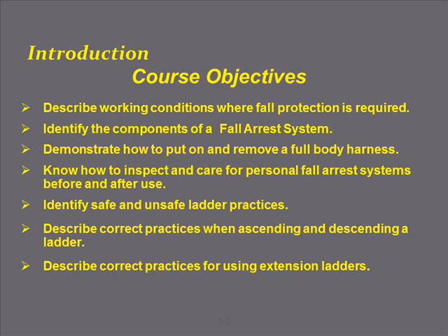Our objectives for the fall protection section are to describe working conditions where fall protection is required, identify the components of a fall arrest system, demonstrate how to put on and remove a full body harness, know how to inspect and care for personal fall arrest systems before and after use, identify safe and unsafe ladder practices, describe correct practices when ascending and descending a ladder, and describe correct practices for using extension ladders.